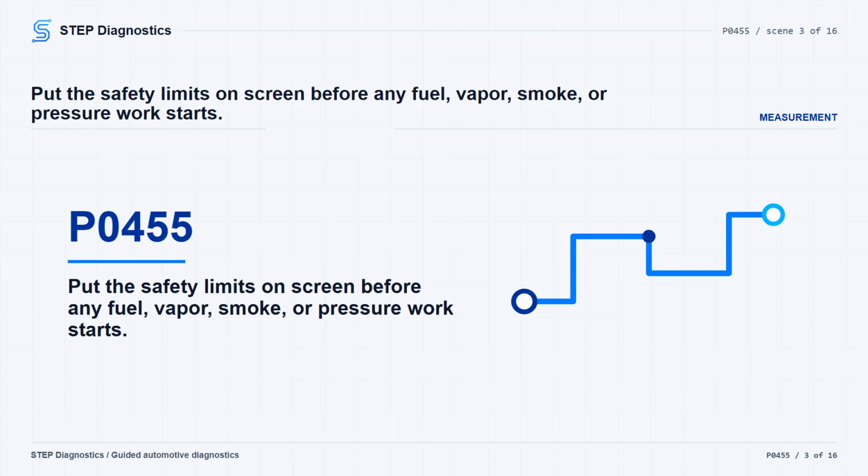If you are using the EVAP leak detector with onboard nitrogen generator 218-522C or an equivalent unit, the fuel level must be less than 85% full. Do not apply smoke to the EVAP leak detection control module. Also, do not rely on soap solution around the fuel cap or capless filler inlet, and do not use a hydrocarbon analyzer as the leak finding method here. During smoke work, remember that the smoke and airflow will not pass through liquid fuel, and liquid fuel may be sitting in the filler pipe.